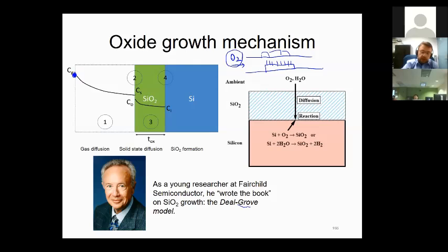And it will have higher concentration, and it will go down to the lower concentration. We know what this is. This is just the diffusion process, diffusion of the oxidant, of the gas. So it will go down to the surface of the silicon dioxide, but that's the key thing. It will not stop there, okay? It will go into the layer, and it will penetrate.